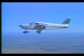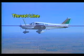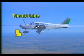To help compensate for this, aircraft designers frequently raise the engine thrust line slightly above the center of gravity. This creates a nose-down pitching force when power is added and somewhat offsets the increase in tail-down force caused by additional downwash.